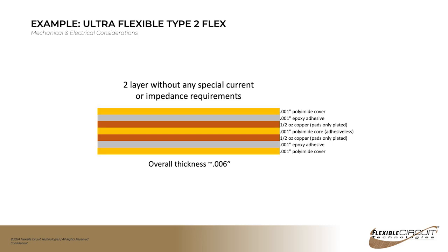This is an animated cross-section of an ultra-flexible two-layer circuit where you'd be using half-ounce copper with pads-only plating, 1 mil adhesiveless polyimide core, and then a 1 mil polyimide cover top and bottom.